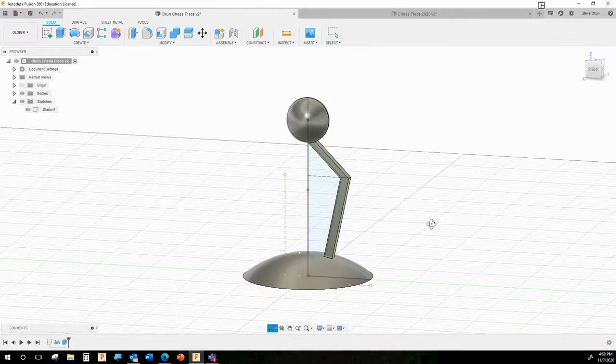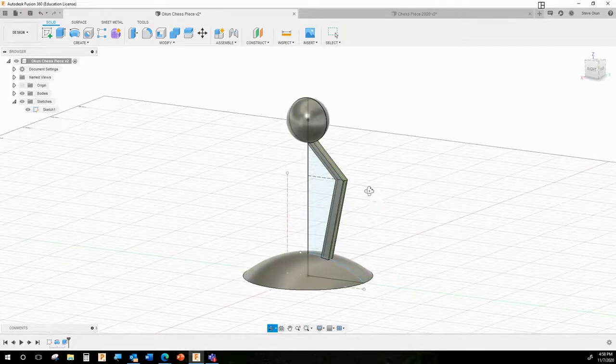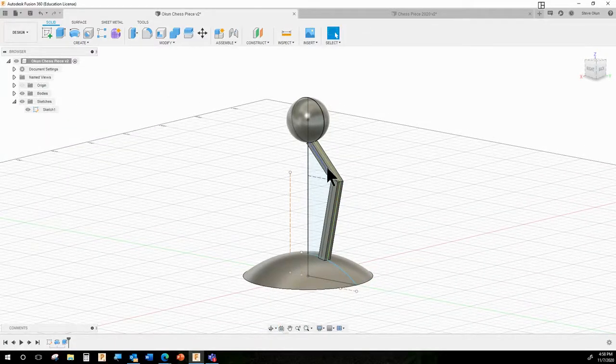And then click OK. All right, so now I'm going to turn this into a pattern, a circular pattern, just like we did on the scoop when we made the grooves. But on the scoop, I made a circular pattern of the sketch. You can save yourself time sometimes when you have a solid piece. Instead of making the sketch a circular pattern and then extruding all of those pieces, you can make a solid piece and turn it into a circular pattern.